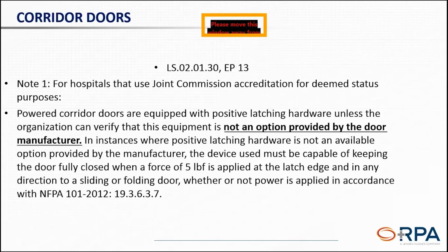If that is not present on your hardware, you would have to do some homework to talk to the door manufacturer, the manufacturer of the operator, the door operator, and verify that that is not an option to add on that latching interconnect. So if you can't find that out, then you certainly have to add latching hardware.